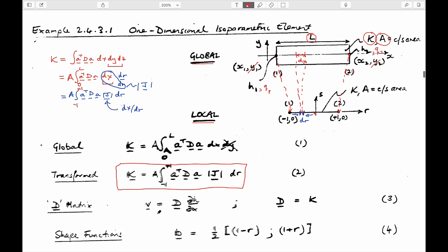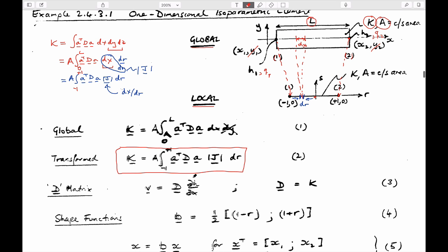So in the same way as before, we want to know exactly what the individual components are. We need to know exactly what this matrix is in terms of the local coordinates, and we need to know what this matrix is as well, and everything else we can get. The conductance matrix, Darcy's law doesn't change, so this would just be a single value. This is hydraulic conductivity, K, not to be confused with a matrix equation. So this is hydraulic conductivity in Darcy's law.